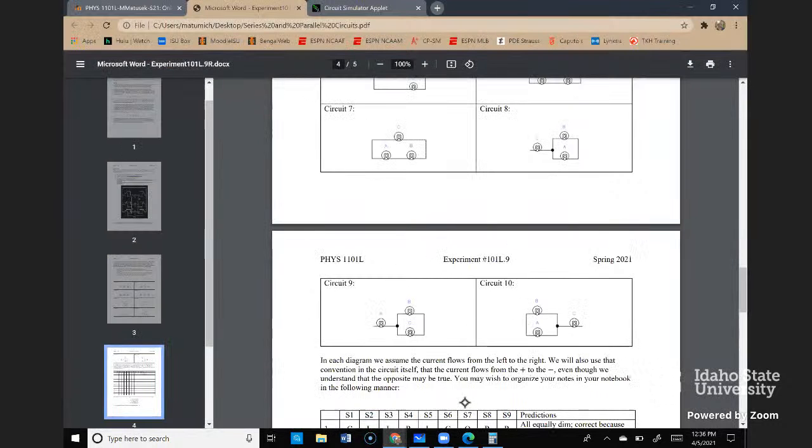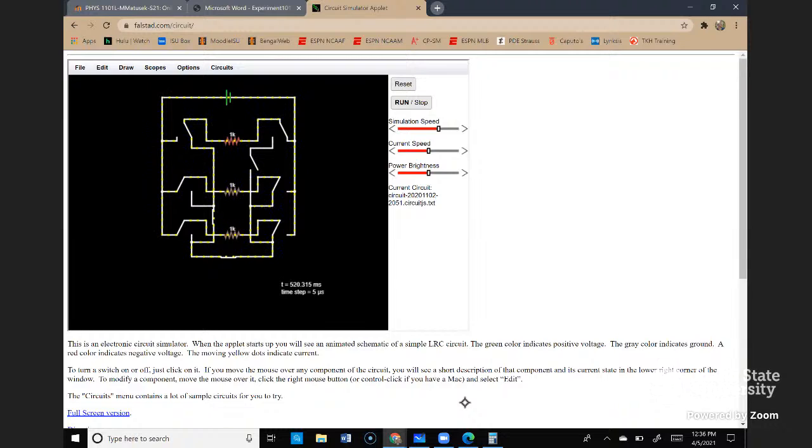Okay, so let's check our circuit, which is the appropriate circuit. You've got the current going through the branch of B and C, but they both combine right here and then are driven back up through A, which goes back to the power supply. Okay, so the power through A is 11.11 milliwatts, which is exactly what we calculated.